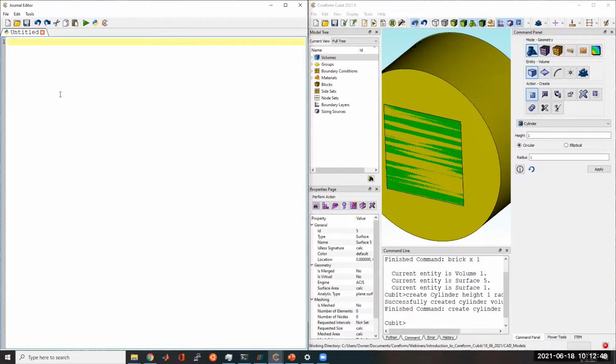So for them, it was a huge jump to be able to say, now I can build a triangle mesh by just sending a command to mesh the surface, and then use a Delaunay triangulation or advancing front to mesh a surface rather than drawing it out by hand. So Qubit started as a command language, almost like a programming language, that accelerated those people's workflows.